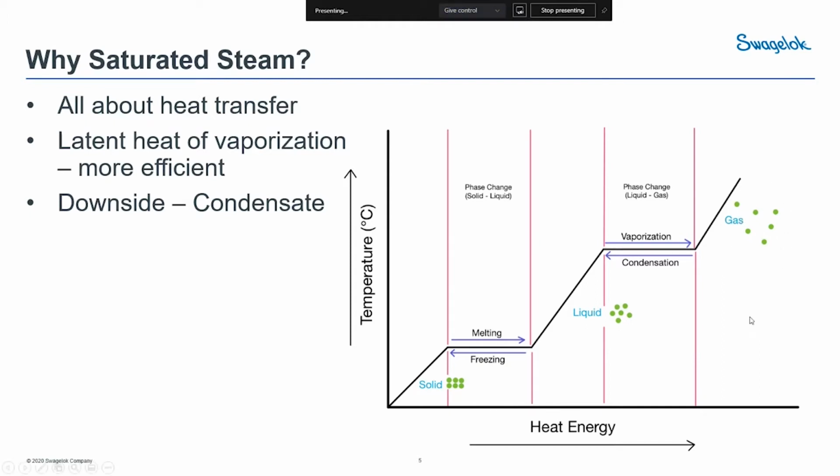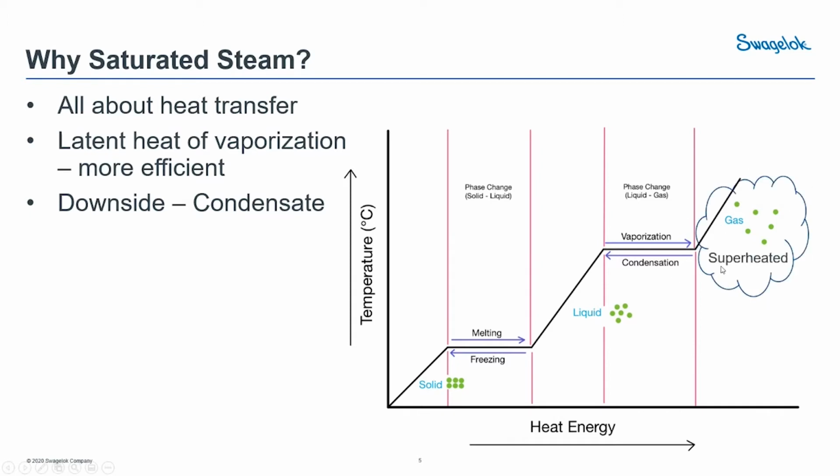And if you look at temperature change only, the superheated steam, anything that's above the vaporization temperature, as you absorb temperature from it, you're going to move down this curve. But if I move down, say 20 or 30 degrees down this line, it's not actually adding a lot of heat to my process. So heat is what we really care about, is energy transfer. So that temperature change represents a small amount of energy transfer.